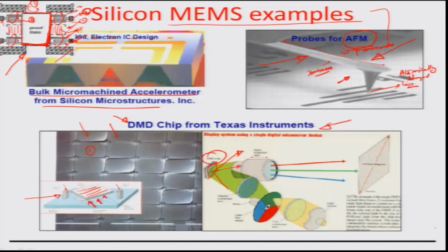So, in a way, by manipulating these various small chips through electric fields, you could transfer pixel by pixel information of an image, and you could formulate an image with a dark pixel or a bright pixel, and that is how things are projected. And the lens would help by magnifying the particular image from a small scale as is obtained in this DMD chip all the way to the wall, which is at probably a higher version.